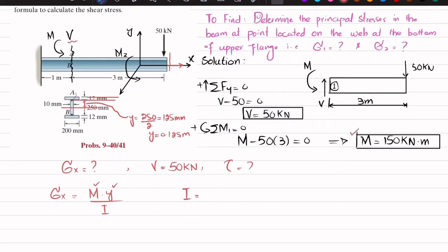So if I take this whole box and find the moment of inertia and then subtract these two empty portions, we will get the moment of inertia of this beam. Generally it is equal to 1 over 12 bh cube. So here I will be equal to 1 over 12, B is its breadth, which is 200 millimeter, and in meter it is 0.2, and height is 274, which in meter is 0.274 whole cube,